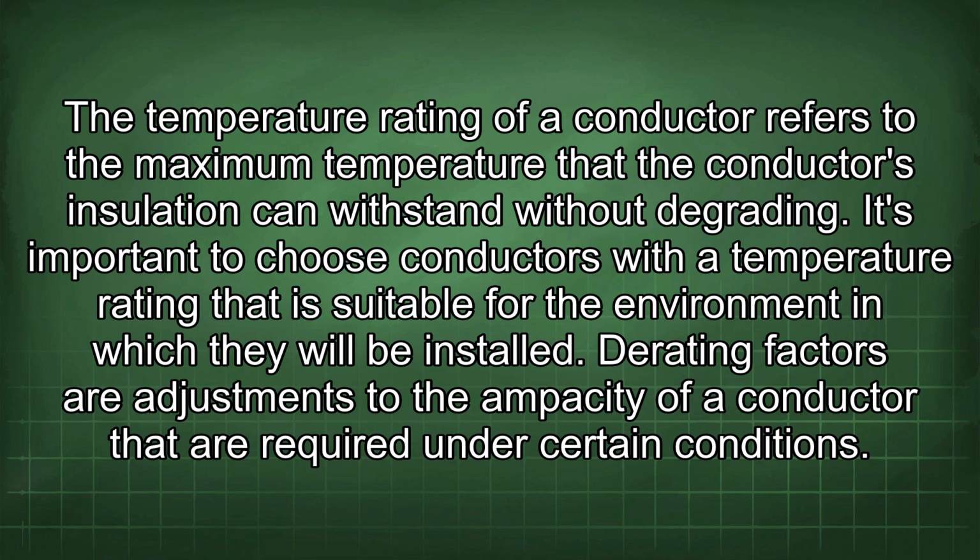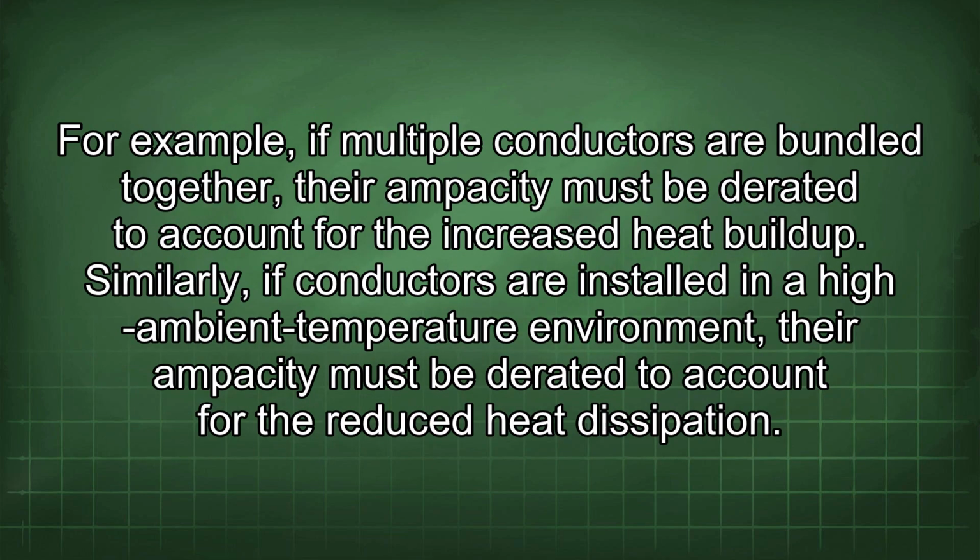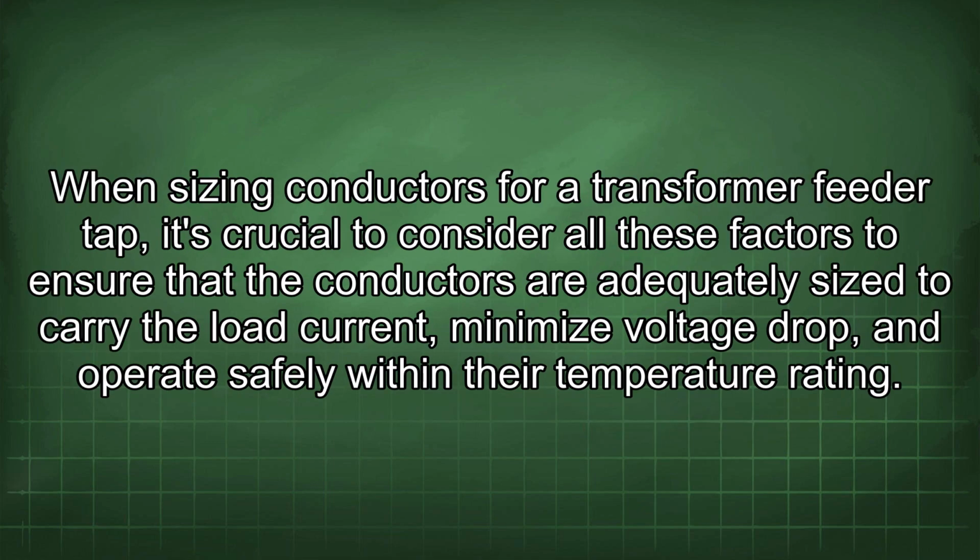Derating factors are adjustments to the ampacity of a conductor that are required under certain conditions. For example, if multiple conductors are bundled together, their ampacity must be derated to account for the increased heat buildup. Similarly, if conductors are installed in a high ambient temperature environment, their ampacity must be derated to account for the reduced heat dissipation.